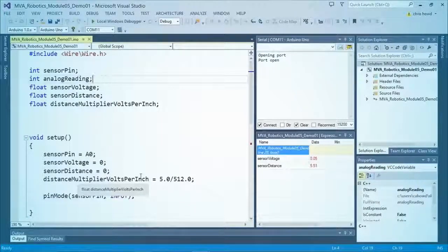This brings up a great point. For these sensors, they're going to report a distance of 6 inches for values less than 6 inches. So it will detect that something is there that is less than 6 inches away, but it will tell you that it's 6 inches away. So you always need to understand what your sensor is going to return. That's true for all sensors. You should understand the data they're returning.